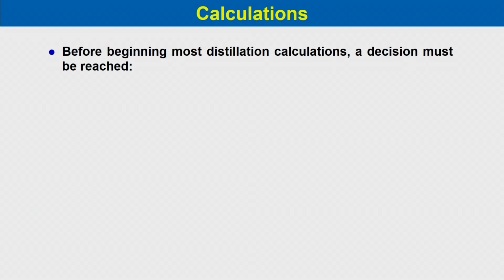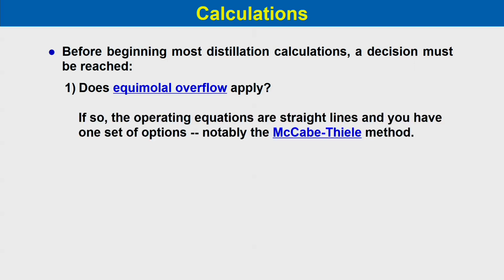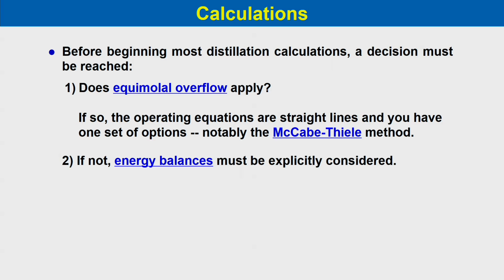Before beginning most distillation calculations, a decision must be reached: does equimolar overflow apply for this process or for this application? If so, the operating equations are straight lines and you have one option, that is the McCabe-Thiele method of determining the number of stages, which is a graphical method. If not, then energy balances must be explicitly considered.